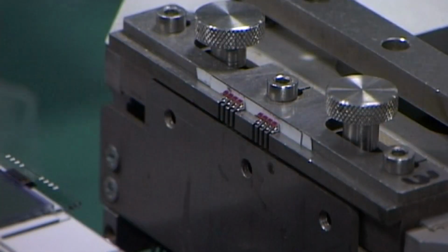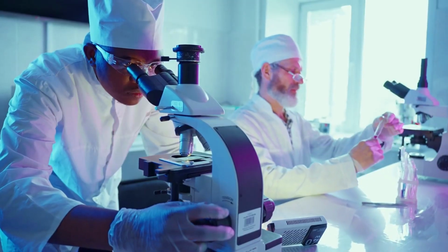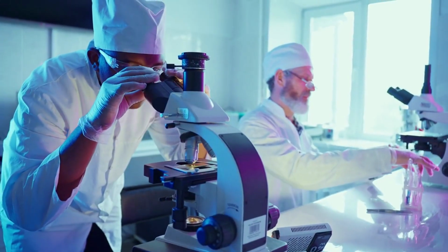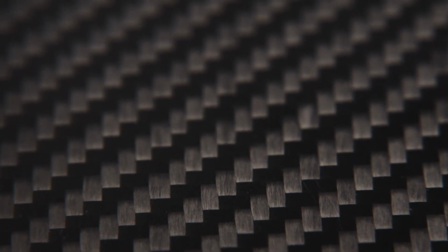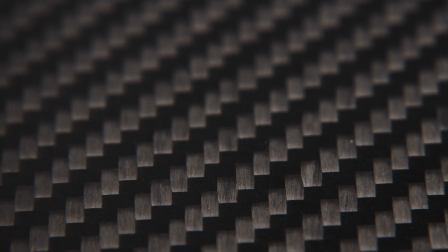For this reason, modern production lines include advanced monitoring systems that constantly track fiber tension, furnace temperatures, and material quality throughout the entire process. The precursor material itself also plays an important role in the final cost. The most common precursor, polyacrylonitrile, must be produced with high chemical purity and consistent molecular structure. Any variation in the precursor material can influence the performance of the finished carbon fiber. Despite these challenges, carbon fiber has become one of the most important materials in advanced engineering.